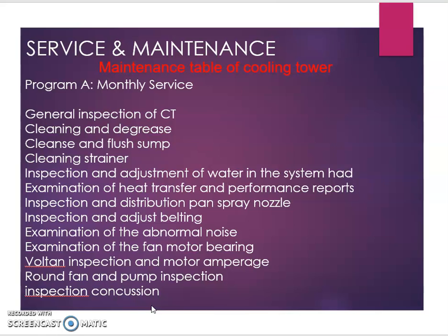Inspection and adjusting of the belting, if they are using belting from the motor, and then examination of abnormal noise. Is there any too high noise there, which is abnormal? Examination of the fan motor bearing, the voltage inspection and motor ampere, which is the running amp of the cooling tower, fan and pump inspection, and also inspection of the condition.